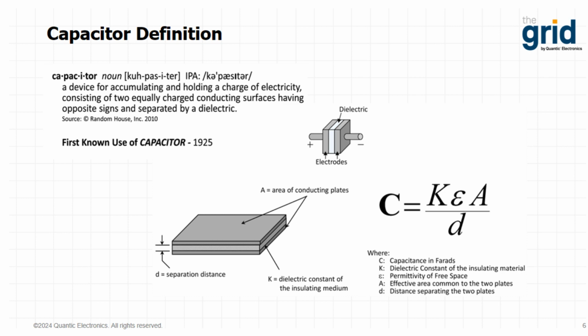Even though the dielectric constant of some popular ceramic materials is up to 1,000 times that of some of the most popular polymers, those same polymers have higher dielectric strength, so thinner plate separators can be used. So the technologies are very different, but the end effect is actually quite comparable. There are distinct advantages and disadvantages to each, and that is what we're going to focus on today.